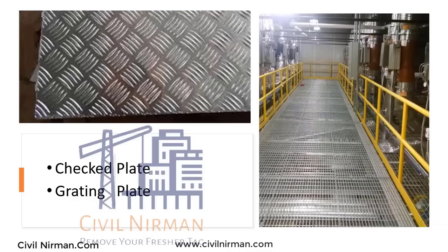Now over here you can see a picture of a grating and a checkered plate. Grating is generally supported on two sides. For the rest of the two sides, it can be freely suspended, since the main bar will be in only one direction, and in that direction only we need a support. While when it comes to a checkered plate, we have to provide welding on all four sides of this particular plate. So structural members should be provided in such a way that support is provided in all directions for this.